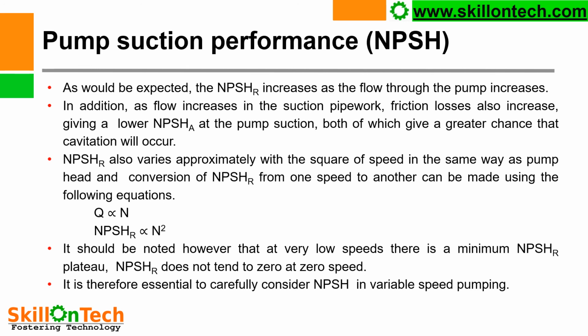So when variable speed motors are used for pump operation, this NPSH must be carefully considered. The pump shall be designed and installed in such a manner that NPSH available shall always remain more than NPSH required at all the speeds.